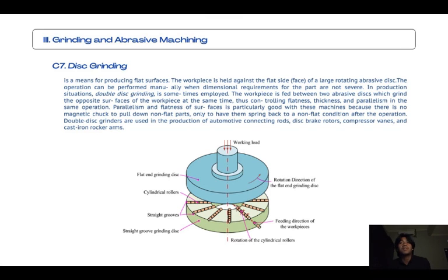Okay, next is abrasive flow machining, or AFM. It uses a viscous putty-like abrasive medium which is pumped so that it flows against the workpiece. The abrasive particles in the medium rub against the workpiece, gently removing surface material. The process is used to round sharp corners, finish edges, remove recast layers from EDM or laser machining, polish surfaces and remove burrs.